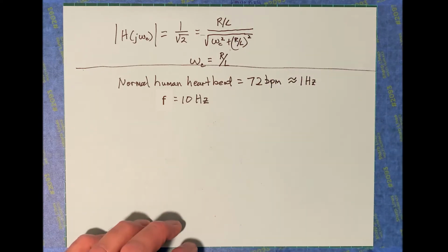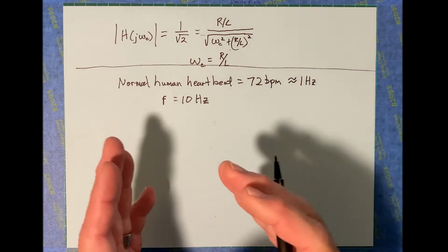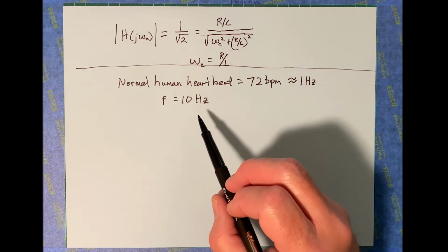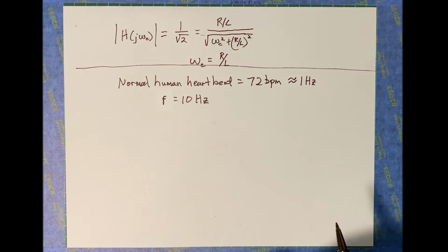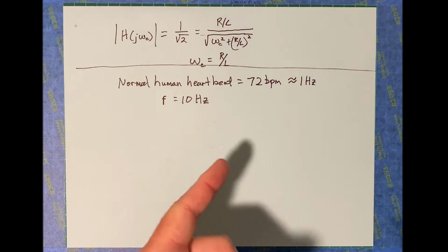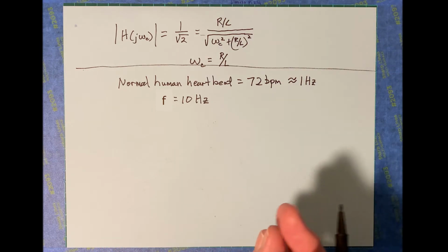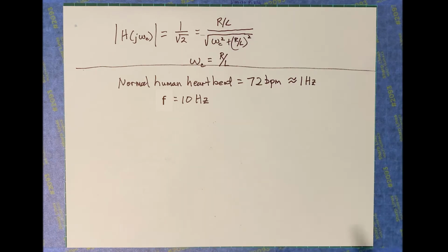We'll make a cutoff at 10 hertz, and 1 hertz is certainly underneath that. But this 10 hertz cutoff frequency is going to remove noise that is also very ambient in the environment, and that is 60 hertz. That's the electrical frequency that comes from electrical devices humming, lights humming, and so forth. So a cutoff frequency at 10 would cut out the 60 hertz and other frequencies around there.